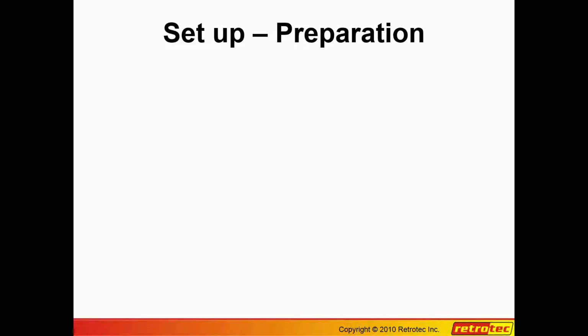So you will be testing the intentional openings in the same fashion that you'll be testing the building, because if you don't seal the intentional openings properly, they will be measured as if they're unintentional, and it's going to affect your overall result. So it's really a matter of experimentation and the use of air leakage devices that we'll show you later to find out how they should be set up.